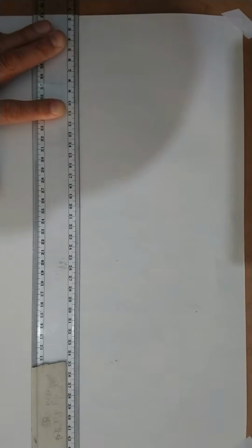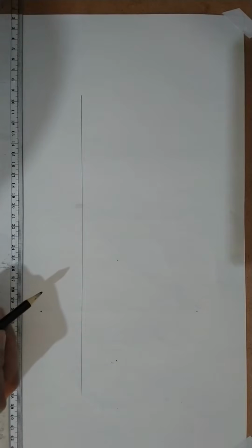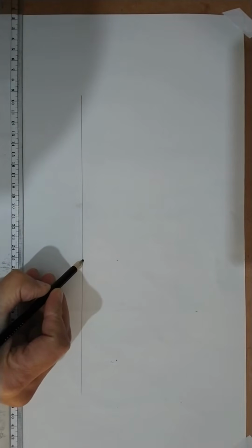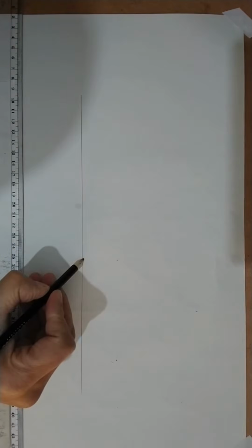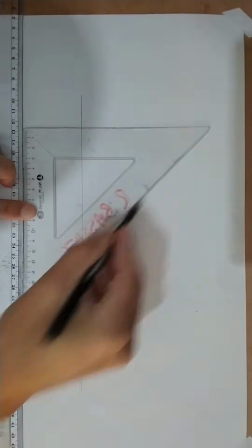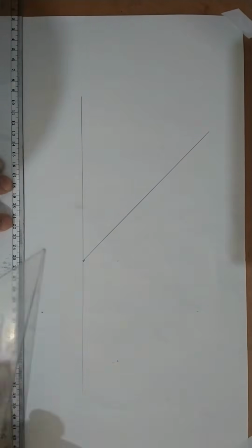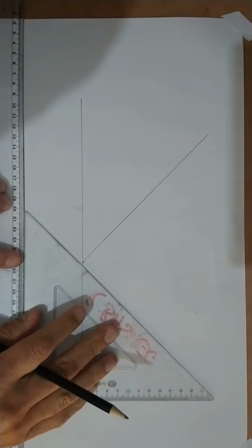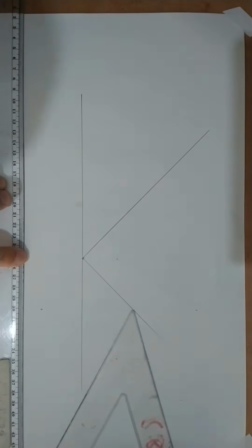So what you're going to do, if this is your page, you're probably going to set up halfway. Don't start low, because you've got to have a top view at the bottom here. So you're going to start in the middle, and you're going to draw an XY line there. And then you are going to create the points on which the drawing slants, right? The slanted point. And because your drawing slants on a 45, you're going to draw that 45-degree line like that, faintly. And for it to be a 90-degree base, it will be 45 to that side.